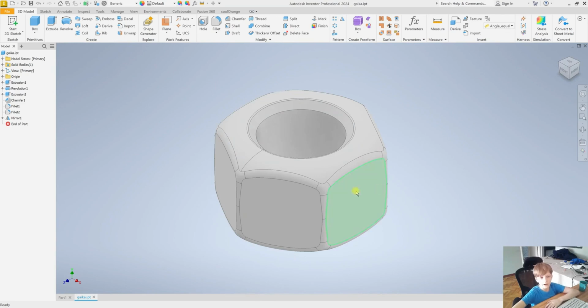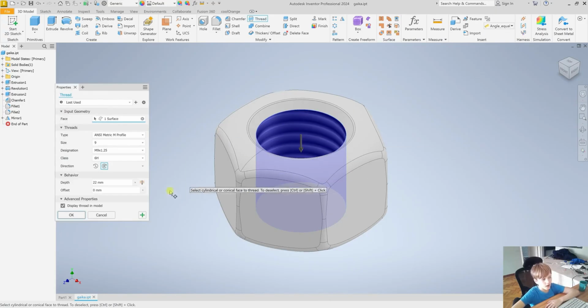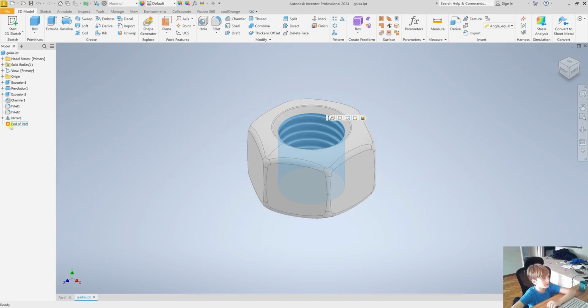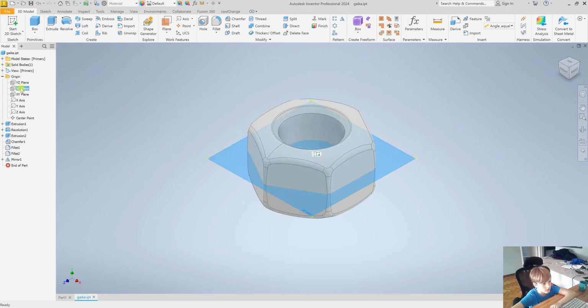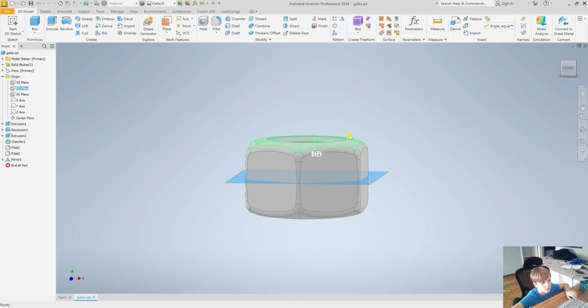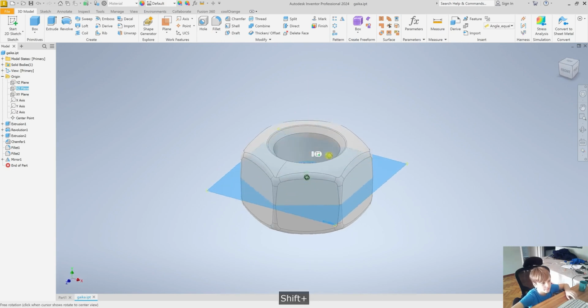In Autodesk Inventor, the thread is initially made as an image. See? But if you want to print your nut, it's better to make it as geometry. I've recorded all the dimensions of a real thread, and now I'm going to create it as geometry, of course. Let's open this up here, click the plus sign next to the origin folder. This will open up a list of planes, which will make modeling more convenient. Let's go ahead and select the XZ plane, which is the horizontal plane, to make an offset upward from it, and from there, we'll begin the process of carefully drawing out the thread profile.